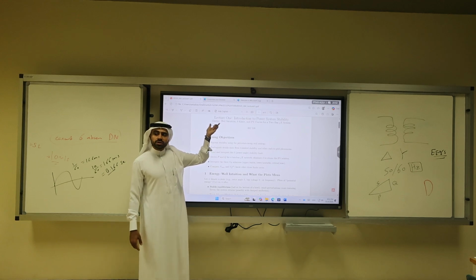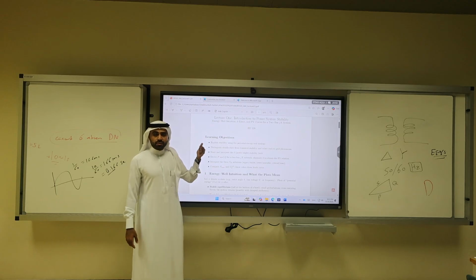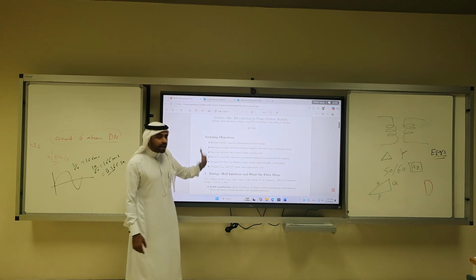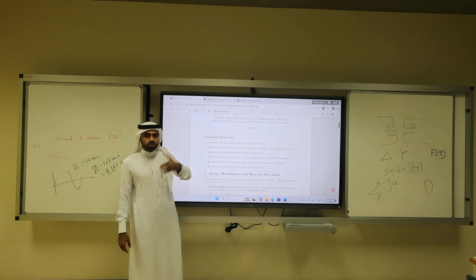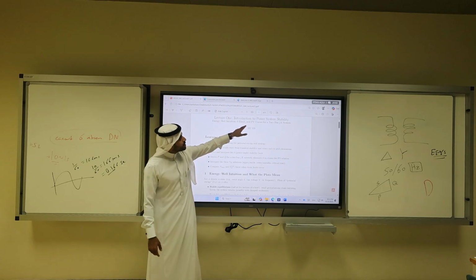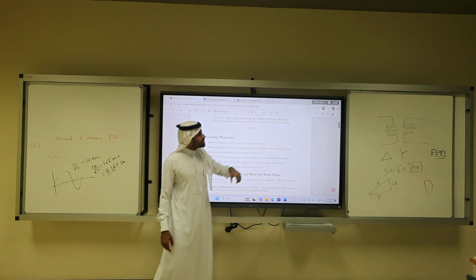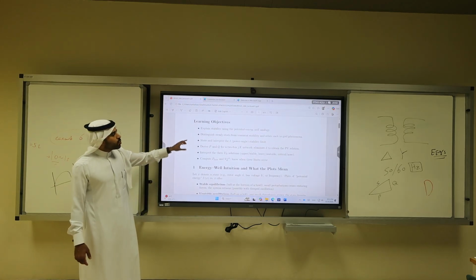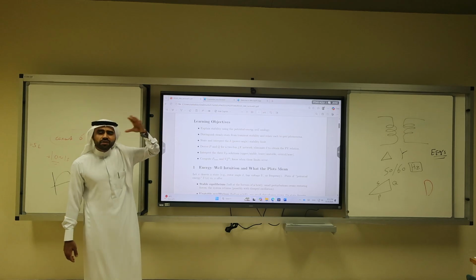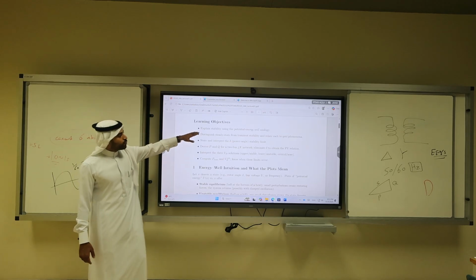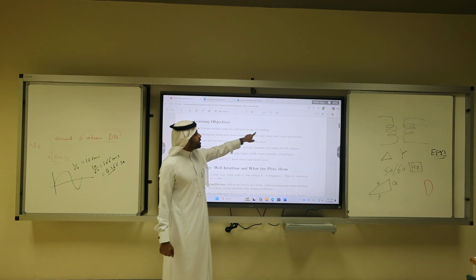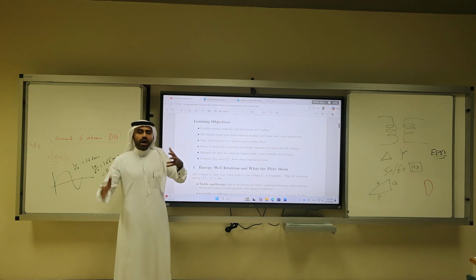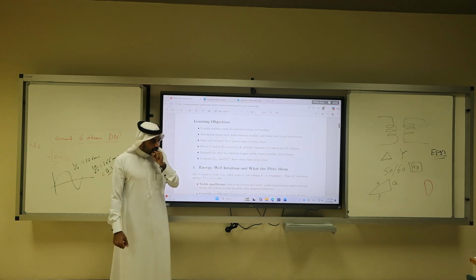We're going to introduce the energy well intuition today, and yes, in the exam I might ask theoretical questions. Explain why, not only problems. The delta limit, PV curves for a 2-bus system. That's a simple system. I'm going to start with the objectives of this very short handout, which is to explain stability using a potential energy well analogy.